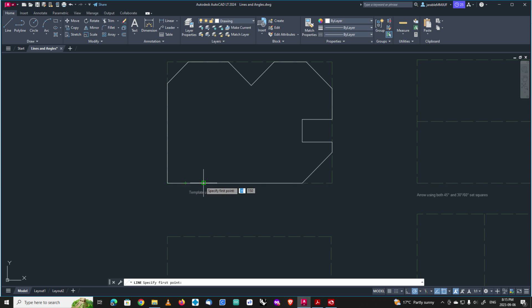I'm going to hover along here until I see the term end point. And you can see right there that it snapped to the end point of that line that I drew. And I'm going to go up by 32 and press enter. So this is where my line will be. So I did this, that line segment. That's why I drew all those little line segments, so I would have these little reference points.